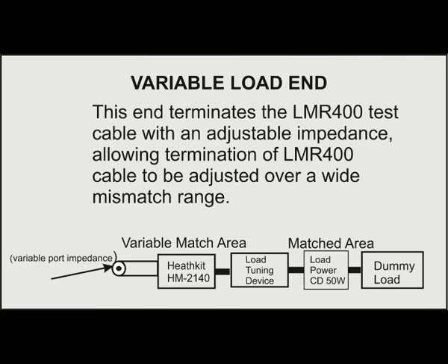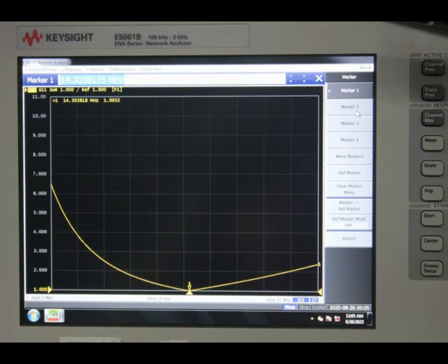But this just is a way that we can measure the power delivered through the coaxial cable into the load when the coaxial cable under test is mismatched. In this case, I'm going to test the cable two different ways. One way is with the load adjustment matching network so that the cable's terminated in a 1-to-1 standing wave ratio at the operating frequency.